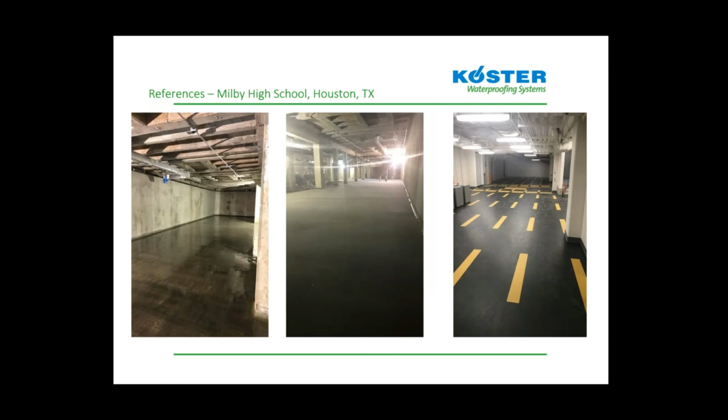So here are some pictures. Picture on the left is the floor with the moisture mitigation coating installed. The middle picture is after we installed the self-leveling underlayment. That product is a KOSTER SL Premium. And on the right is after the flooring has been installed and the room has been repurposed. So we're able to preserve a building that was almost 100 years old and repurpose an old, rundown, abandoned basement into a usable space, a conditioned space for the school and for the students.